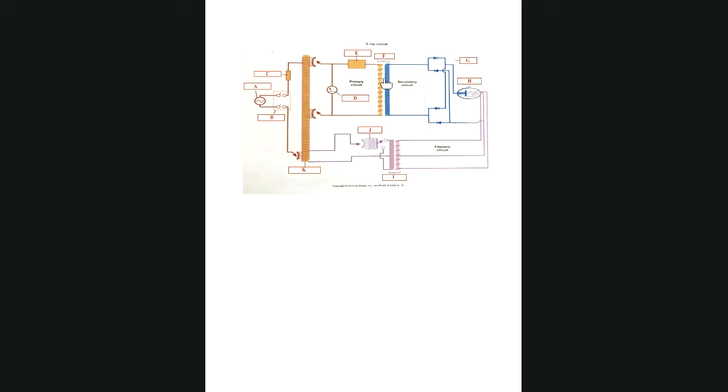Okay, so then here we come up to the step-up transformer. Like I said, you see how many fewer windings there are on this primary side than on this secondary side. That's where the transformer law comes in, where we have NS over NP, the turns ratio, equals VS over VP, voltage secondary over voltage primary.